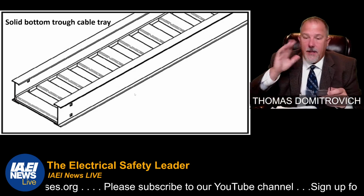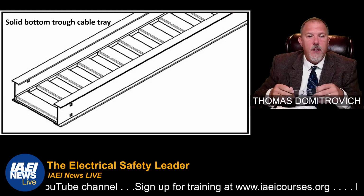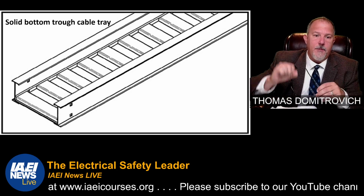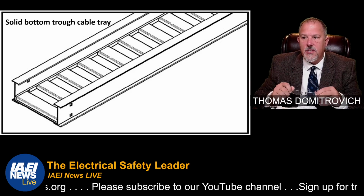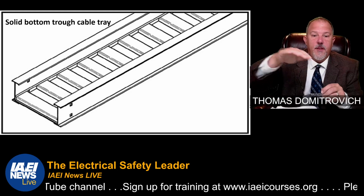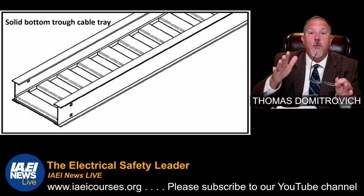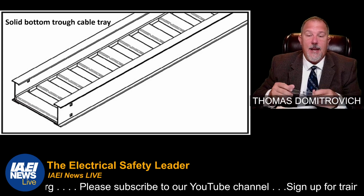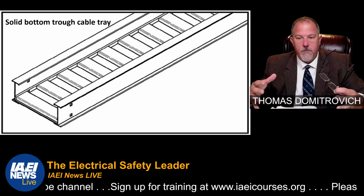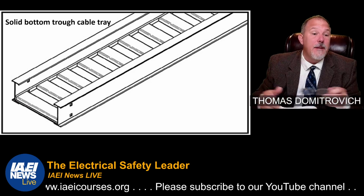Now on your solid bottom, these are all structural considerations for the cable tray itself. From a solid bottom perspective, if you have a large number of small diameter conductors, that's where you'll typically see a solid bottom trough cable tray. They usually come with covers, like wraparound covers, because in some cases you might have to worry about EMI, radio frequencies, especially if it's data cables. The smaller conductor is typically going to be your data cables. So there are methods to build a quote unquote Faraday cage around that, just for EMI or RFI considerations. You're shielding, basically.